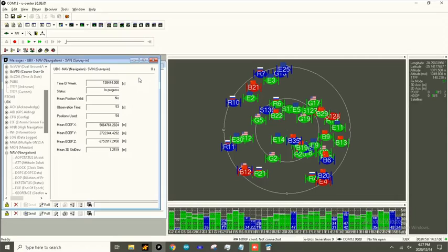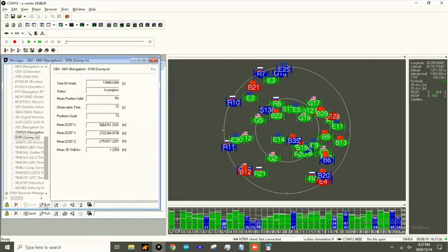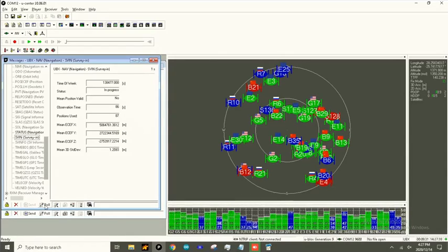So you'll see it's not always automatically updating the values that you see. If you want to manually see or get a new update of the current survey progress, we can just poll the receiver to receive new data. So it's already about 75 seconds in. You will see that the mean 3D standard deviation is already down to about 1.2 meters. And we will just allow the survey progress to continue until it reaches either 180 seconds and then less than 1 meter standard deviation.